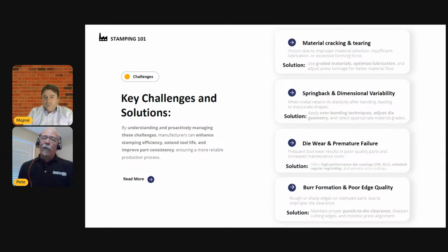And turning that nozzle off at that particular part in the die changed the frictional characteristics in that station. It was a forming station. And so it changed the stress state in the part. And we had a little bit of different relaxation of that. So where somebody might think, we didn't change anything in the process, little things like that can make big differences.